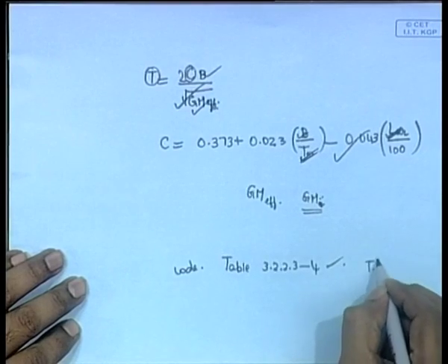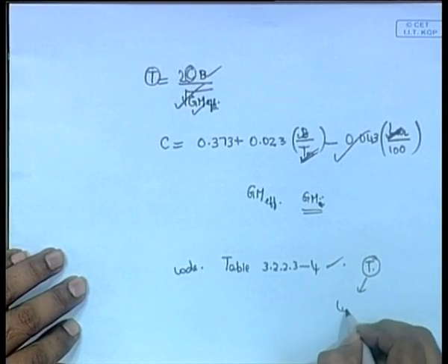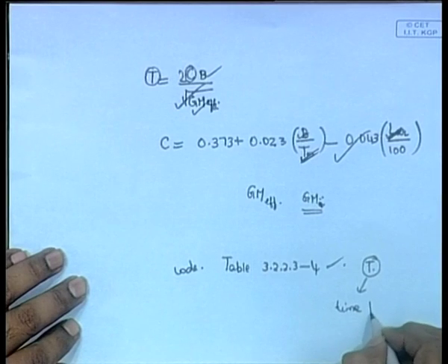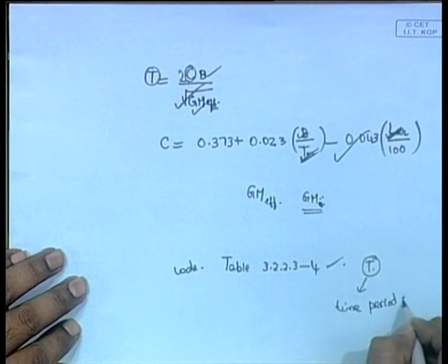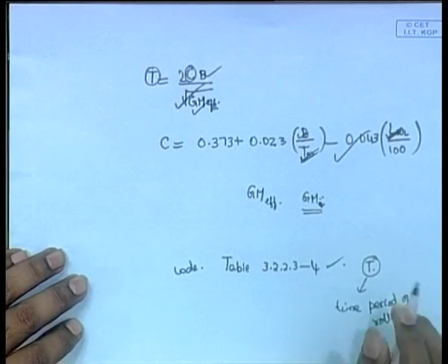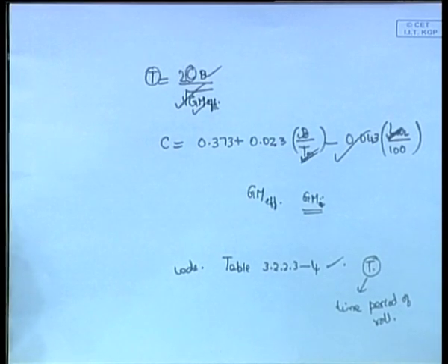which is the time period of roll, please remember, note what each thing is, it is the time period of roll, which is a function of the hydrostatic particulars of the ship. It depends upon B, the breadth of the ship, it depends upon C, which also depends upon the length of the waterline, it depends upon the draft.